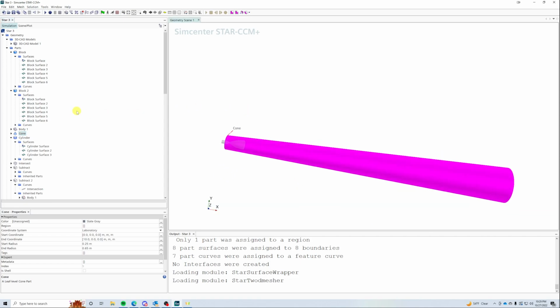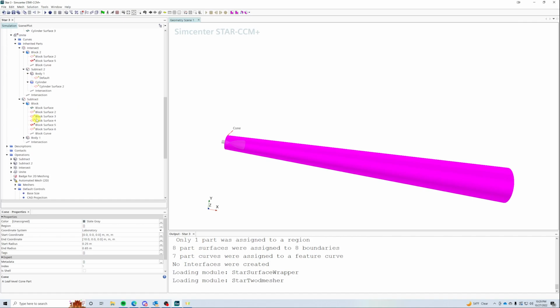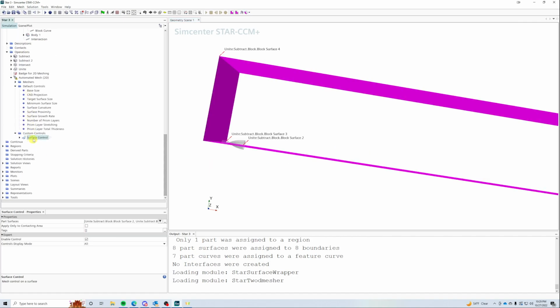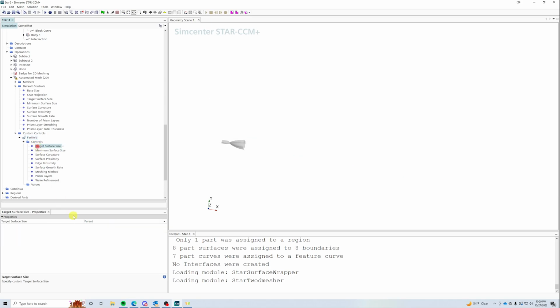There we go. So we're going to have a volume refine on this cone here. This is our far field refine. We don't particularly want it to be a very coarse mesh or very fine mesh here. We also want to disable prism layers. Prism layers disabled. We're going to crank this up to something like 1600%. And minimum base size is going to be 100.